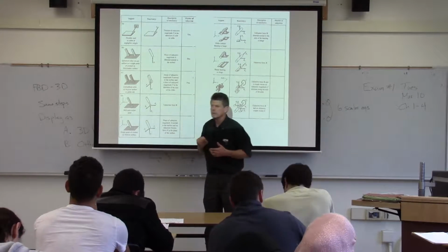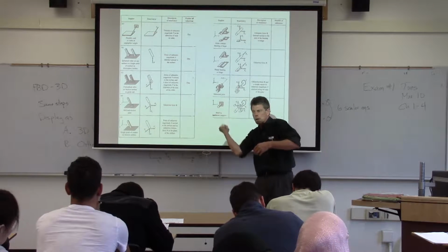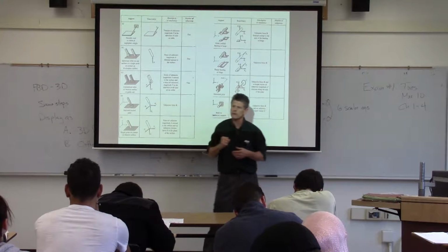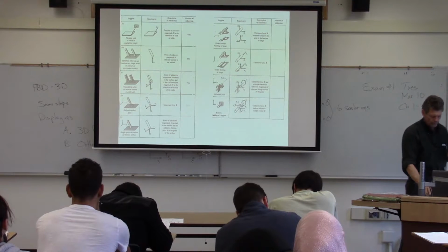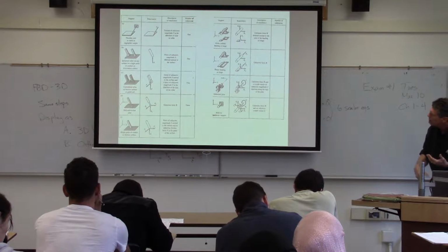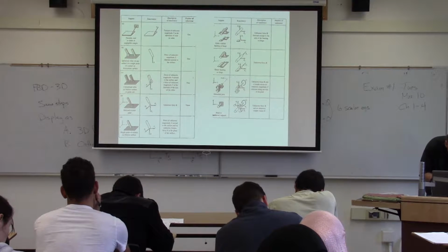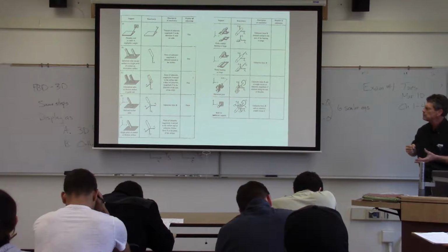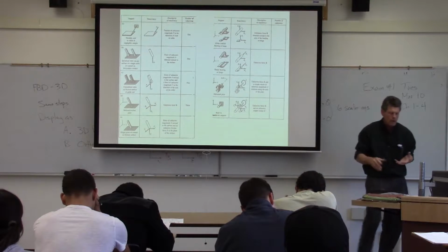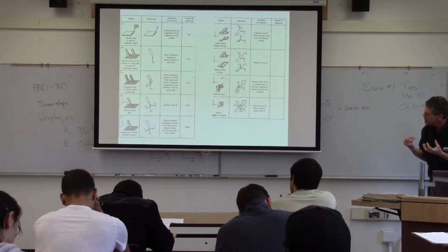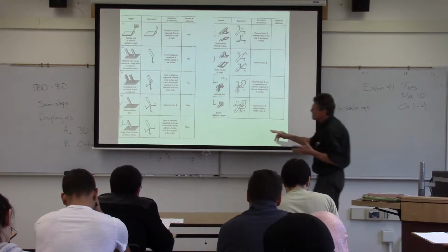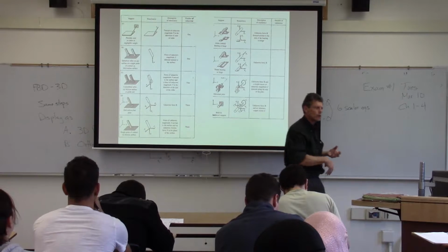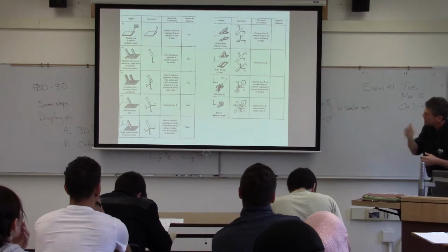Finally, ball and socket. A ball and socket is basically going to allow me to rotate, but I'm not going to be able to push through it. I'm not going to be able to go this way, that way, and that sort of thing. So it's going to provide me 3 unknowns. Same thing basically with the next one, which is a rod on a friction surface. The friction is going to keep us from going in any particular direction too, so it's going to provide the same sort of support system. We'll break these up so the x and y components are perpendicular to each other, because we want to feed them into a scalar equation and solve a scalar equation, not a vector equation.